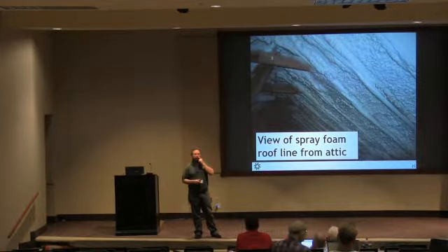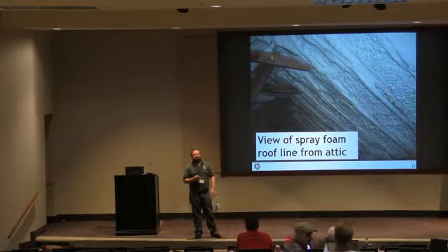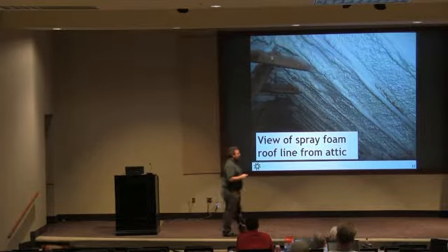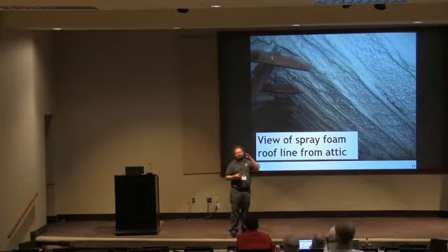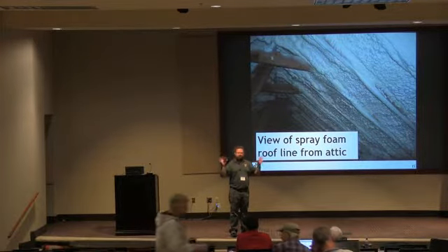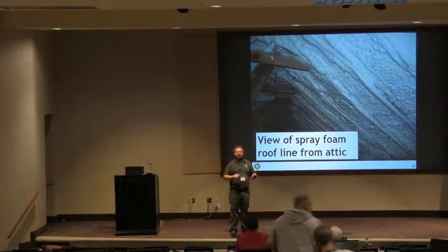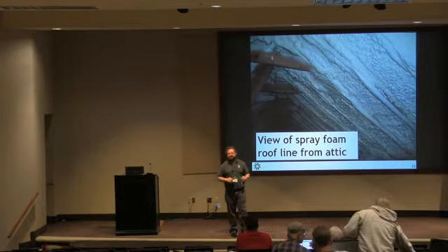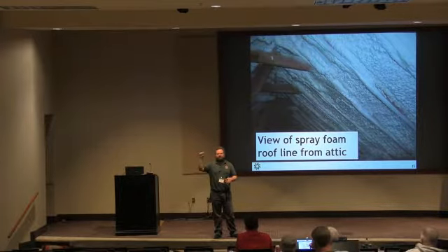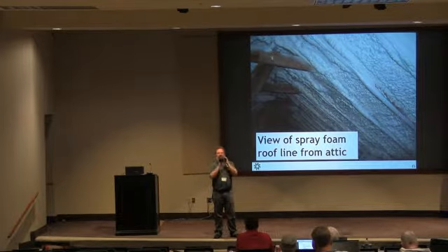On the spray foam, how do you account for the ventilation requirement on the roof decking? Two ways. One is you can get a roof shingle manufacturer that will warranty a roof with a spray foam unvented roof assembly underneath it. And here's how you find them. You find a manufacturer who manufactures roof shingles and also manufactures spray foam. And lo and behold, they will warranty their product installed correctly unvented.